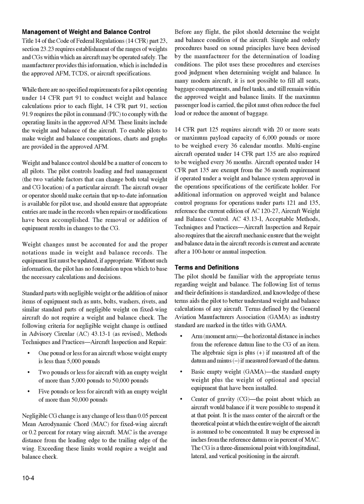While there are no specified requirements for a pilot operating under 14 CFR Part 91 to conduct weight and balance calculations prior to each flight, 14 CFR Part 91, Section 91.9 requires the pilot in command, PIC, to comply with the operating limits in the approved AFM. These limits include the weight and balance of the aircraft. To enable pilots to make weight and balance computations, charts and graphs are provided in the approved AFM. Weight and balance control should be a matter of concern to all pilots.